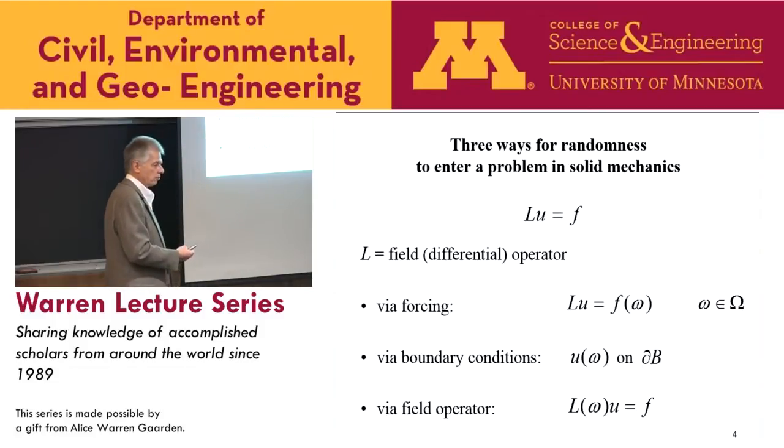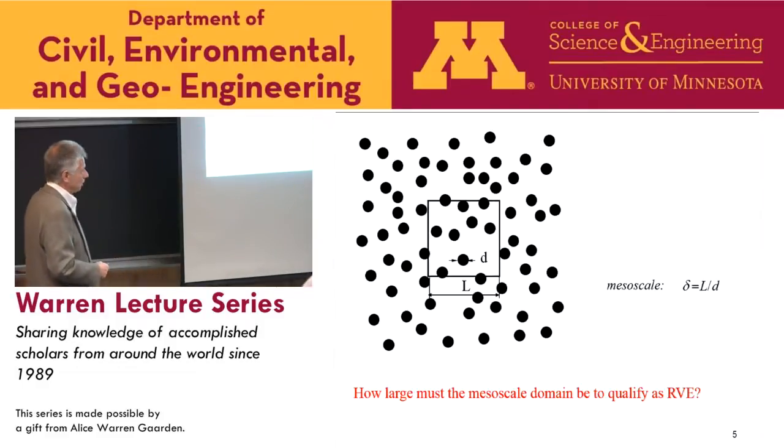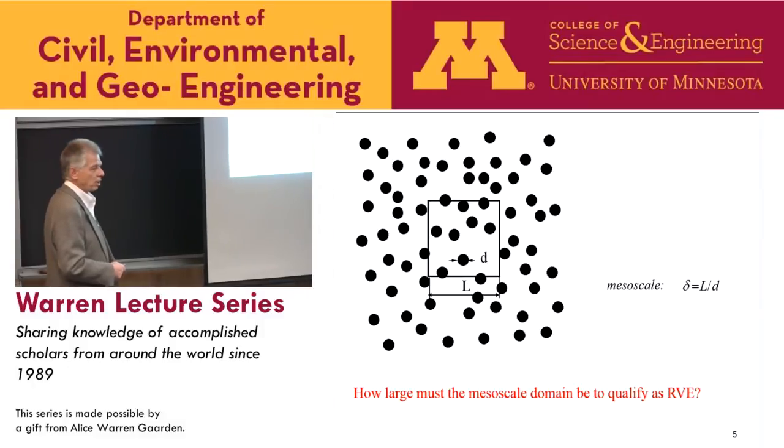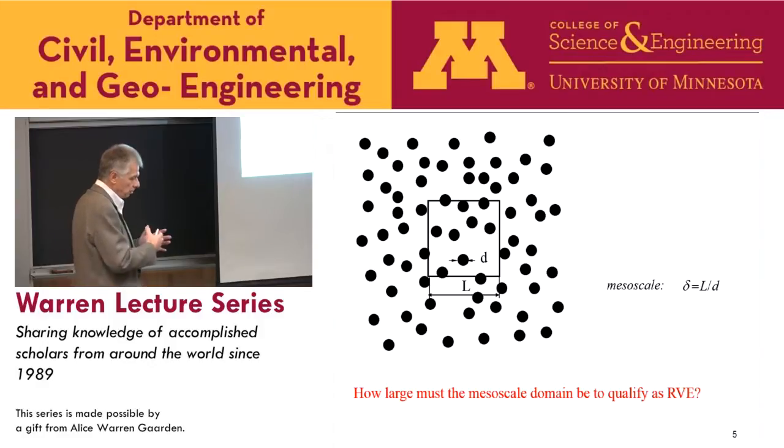Can we even say that we have Lamé coefficients, or would it be more honest to admit the whole anisotropy of the stiffness tensor? So basically, I'm working here under the motto, how big is big enough? This issue, and the classical micromechanics always goes for this macroscopic response here, whereas I will be describing a procedure which allows you to get moduli in function of mesoscale, and in the end we're going to get effective moduli of classical micromechanics, for example.